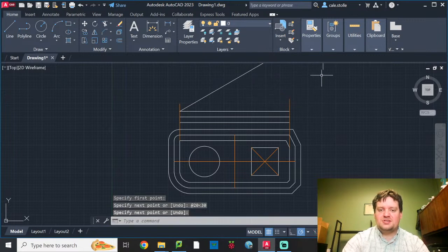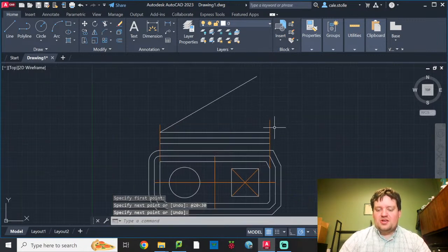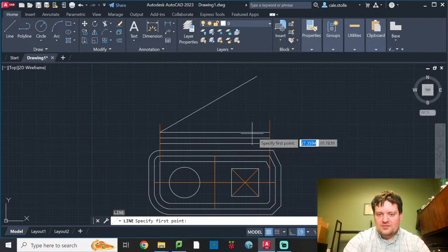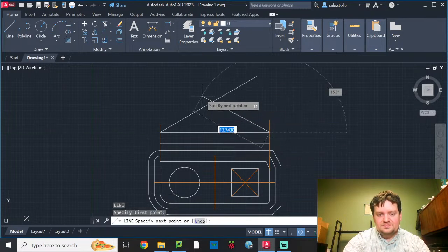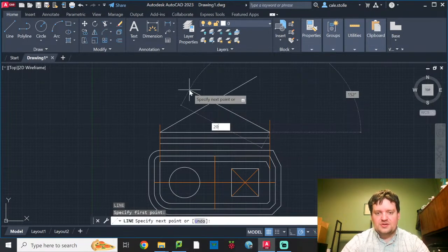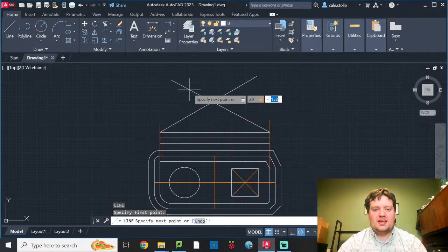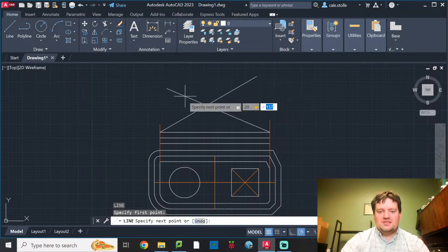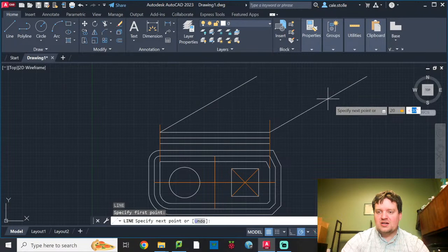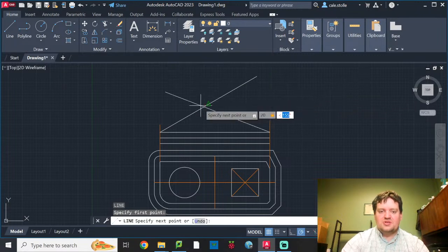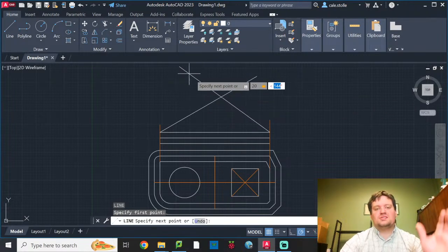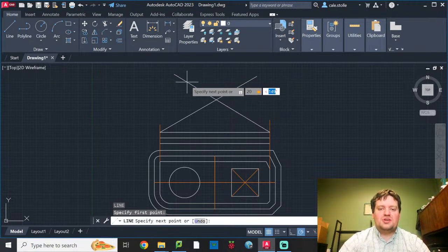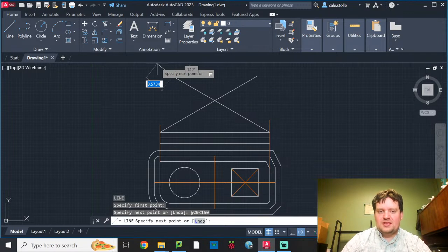So go ahead and hit enter. Well, I want to draw another one, enter. From this side here, I also want it to be 20 units long. I will go ahead and hit shift, comma, to specify an angle. And then over here, if I try to go at this angle, it says there's no 30. 30 is over here. Well, I don't want it to be at 30 degrees. I want it to be at 180 minus 30 degrees. It's using your trig functions there. So I want it to be at 150 degrees. Enter. And then hit enter.